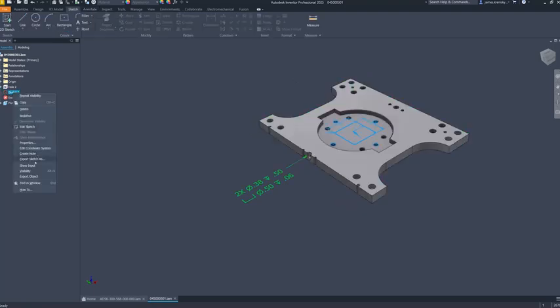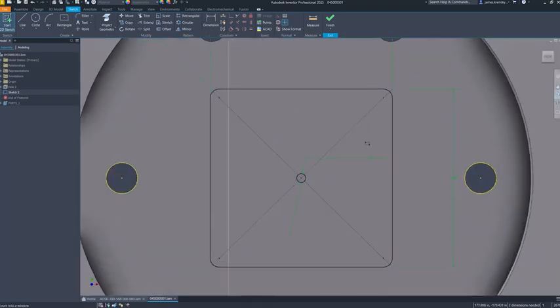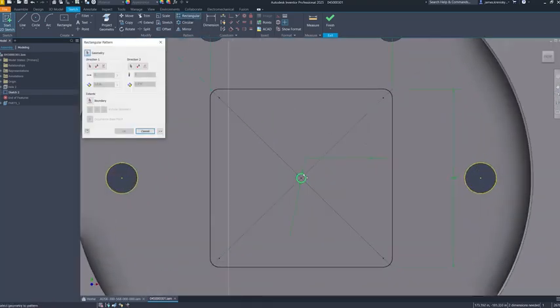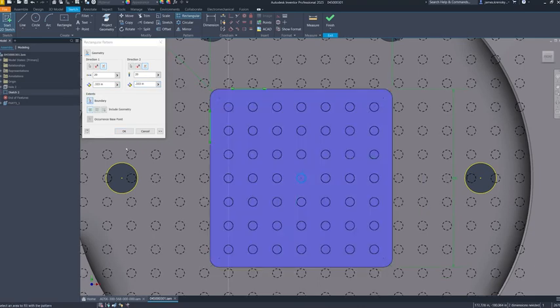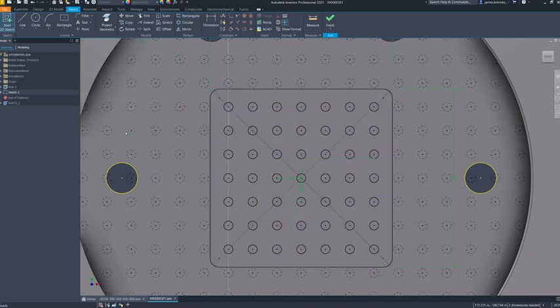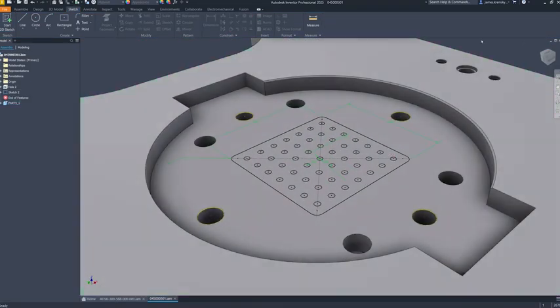The pattern creation process in Inventor has been modernized with the introduction of boundary patterns, featuring a refreshed user interface. This update enables users to generate patterns confined within specific boundaries, allowing for the definition of a region or an area to delineate where the pattern should apply. Any instances of the pattern extending beyond these boundaries are automatically suppressed, ensuring the inclusion of only pertinent instances. This boundary-driven patterning capability has also been extended into the Sketch environment.